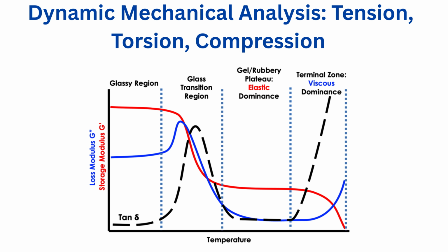Among experimental methods, dynamic mechanical analysis (DMA) is a standard technique for quantitative analysis of cross-linked polymers, e.g., measuring cross-link density. In this method, cross-link density is estimated by applying classical rubber elasticity theory to the elastic modulus measured at the onset of the rubbery plateau.